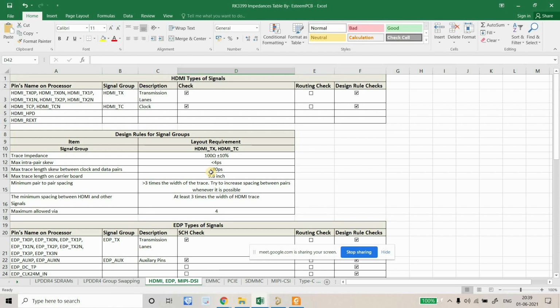You'll realize everything is mentioned here. This is all the information required to convert that picosecond to length. Ideally we'll go for an ideal match, but there is a small offset, or a small tolerance, that we can introduce on the length match if required, in some cases.